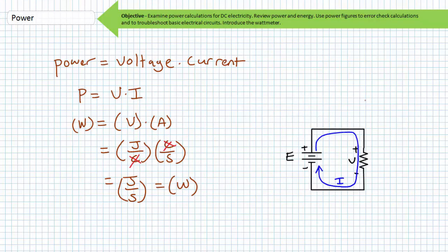Electrical power delivered to a system is the source voltage times the current supplied by the source. This is our power input. Electrical power consumed by an element is the voltage drop across the element times the current through the element. This is our power output. In the case of a single source in a circuit with a single element, where the system is 100% efficient, an obvious oversimplification, the power input to a system is always equal to the power output by a system.